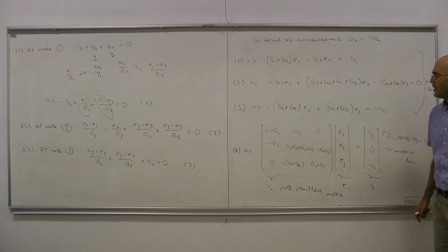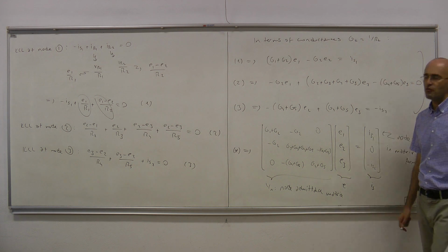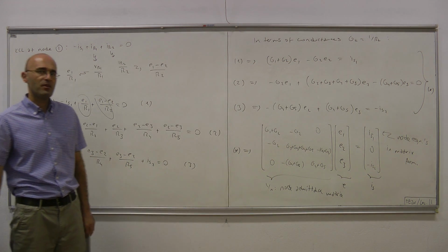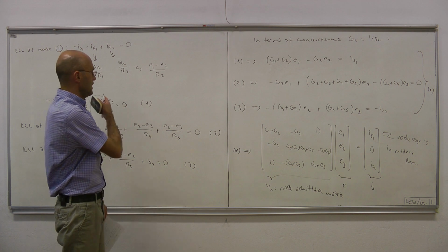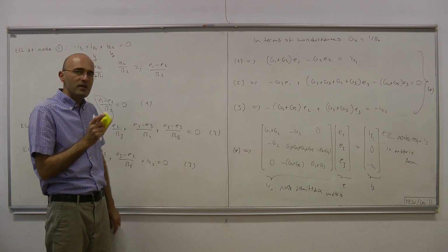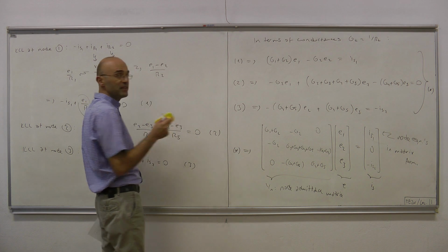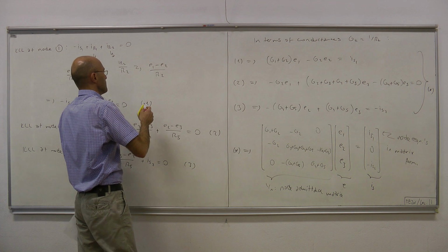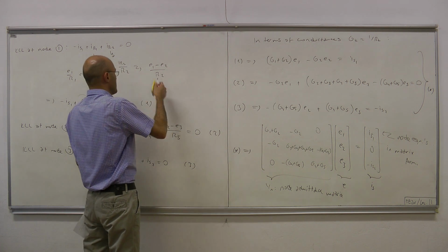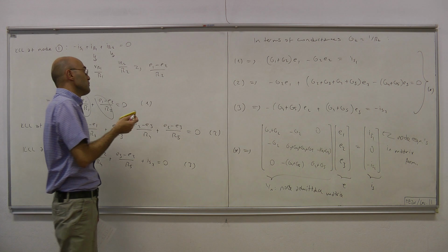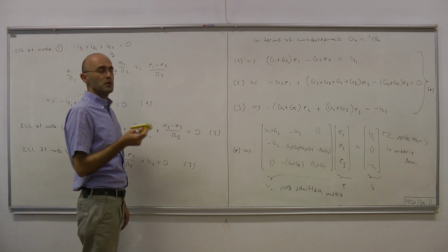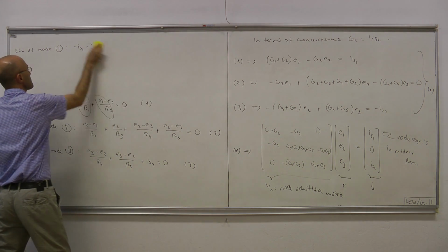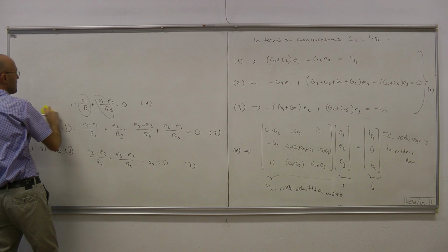Now, note that in the circuit, which was formulated by the node voltage analysis method, we didn't have any voltage sources. When we have voltage sources, we have to be a little bit careful about treating those voltage sources, because it's not straightforward to figure out the currents through them. So we don't figure out the currents through them in terms of node voltages, we do something else. Okay, so let's see what those something else's could be.